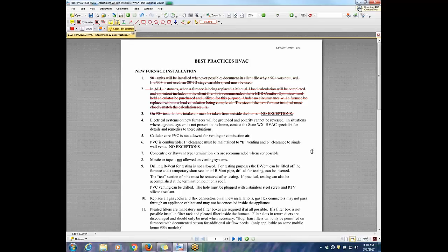Can I throw in my own personal example? Absolutely. I built a new house, and I ran the blower door on it, and I have 1.3 air changes per hour, so it's kind of tight. As I was shopping for my water heater, I wanted a direct vent water heater, and for some reason I couldn't find one. I've learned a little bit in the process that they are available, but I ended up buying a water heater that has the draft inducer on the top, but it takes its combustion air from inside my house.